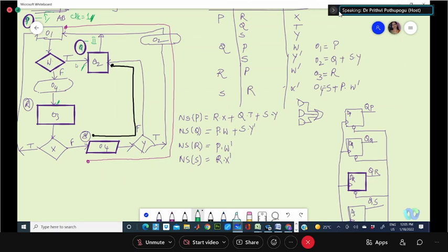Then see, in the same clock of P, we may get only out 1 or out 4, based on the condition of W. Got this? By default, out 1 will be happening. But out 4 will happen on the condition of W being false. But for generating an output which is indicated in a stable state, it needs its own clock. Another new clock applied for this will generate the output. Note that this will be generating the output.